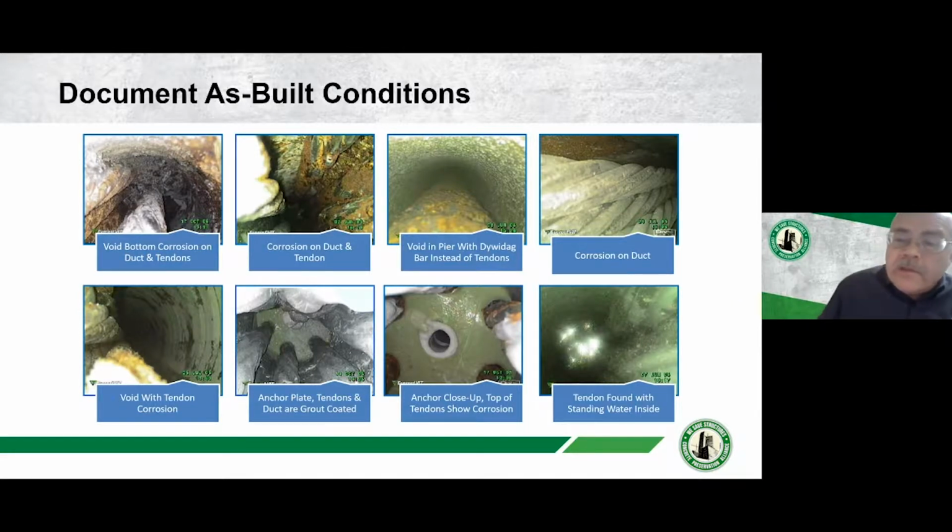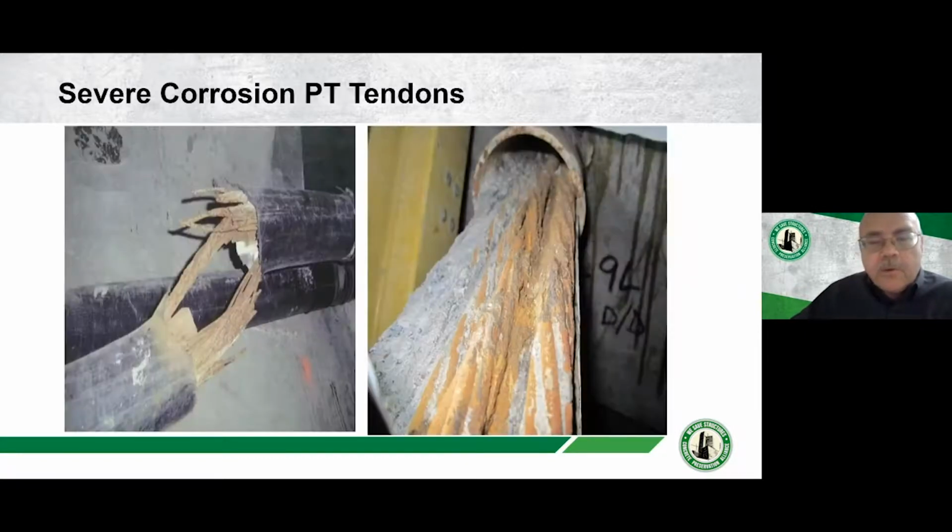And knowing the extent of the voids is a very valuable piece of information when you get into the repair strategy and the quantities for the repair strategy and the condition of the tendons. So we've been taking our system and pushing ourselves with evaluating PT tendons, evaluating pile lengths. Even back in the 90s when the Big Dig was going on in the Boston area, we were one of the first to be doing a lot of the pulse impact echo testing on pile testing when the PVC cross-hole logging PVC tubes were broken.